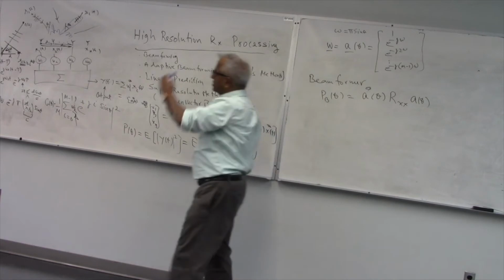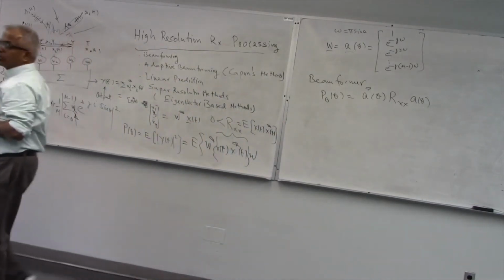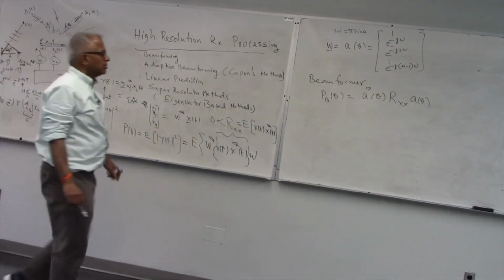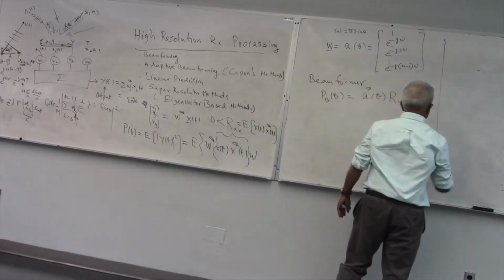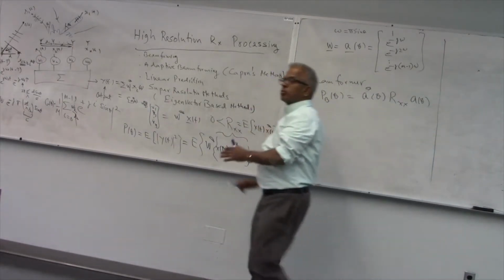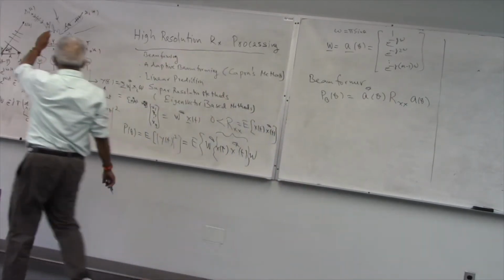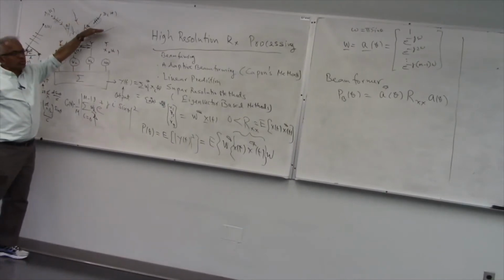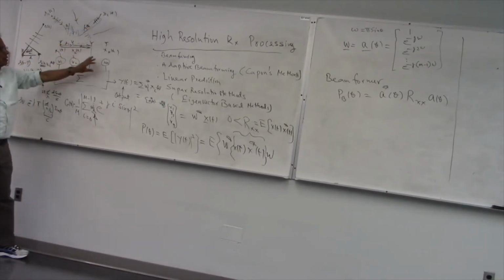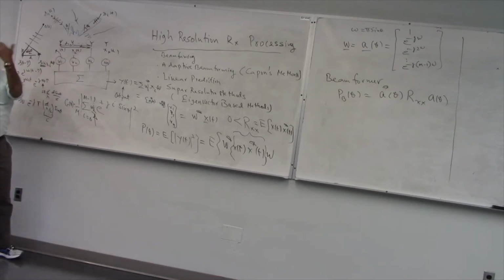So that's the steering vector, electronic steering, so there is no mechanical steering, you just change the weights to zoom in. So what we are doing is in space, we are zooming into a particular direction, right? So you can change this direction to somewhere else by steering the weights here. So you don't need to rotate the antenna.